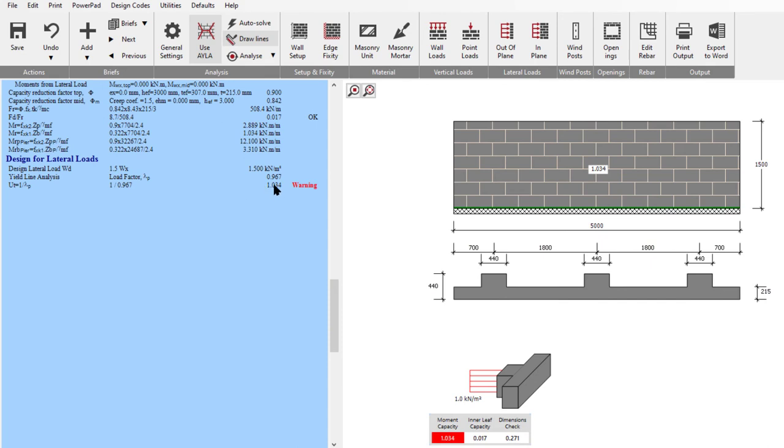And we're nearly there, 3% overstressing. A wee bit less than the wind load, or maybe a wee bit of increased depth in our piers. But as you can see, they're not happy bunnies. My solution here would be to pull these closer together, but that's still a chunky wall. It would probably be a lot simpler to make it slightly thicker, because you only really get this enhancement around a certain width of the wall.